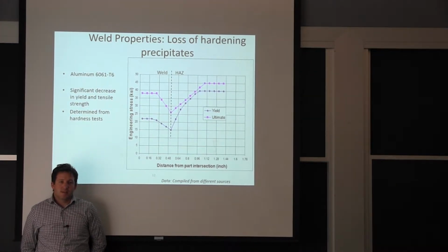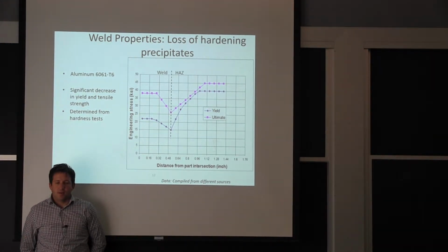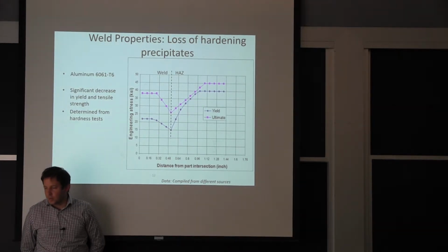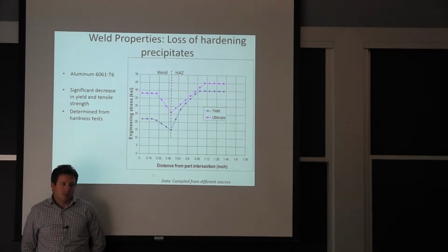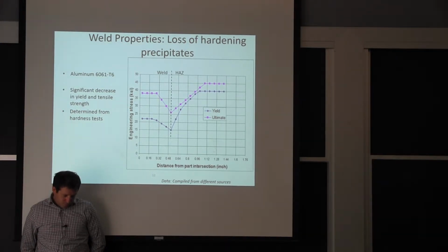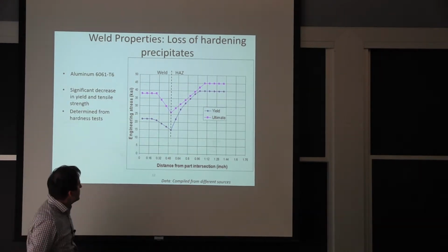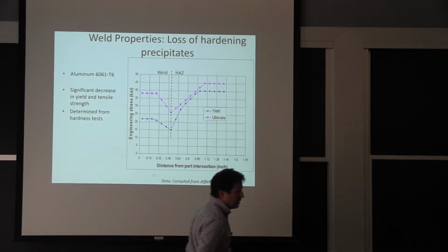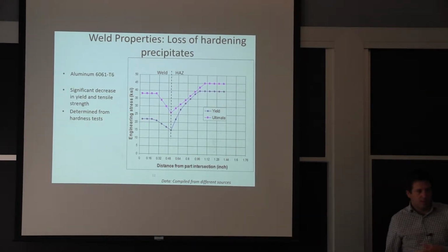So it's very typical that welded joints don't have the strength of the base material. And when I say they don't have the strength, we're talking a factor of 3, especially for cyclic loads. So it's very significant if you're doing a design. The aluminum design manual will give you just about 2 or 3 KSI of allowable cyclic stress for an aluminum joint like those here.